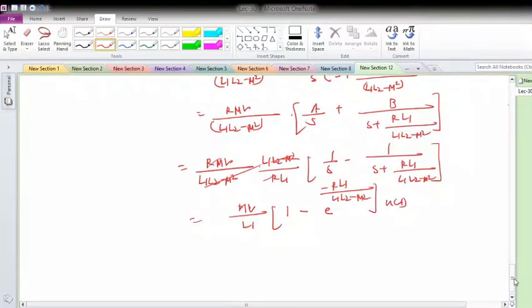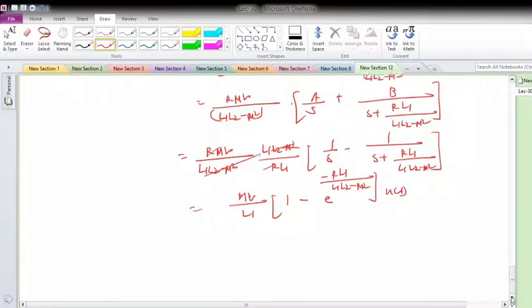Okay, so if we apply an input, and that input is a step input, for example, what we'll get is an exponentially increasing form with some time constant. And why with some time constant? Because of the energy storage element, that is the inductor present over here. So if I would like to draw the graph, what is the input? Input is my step input, and this is v1 of t, and what will be v2 of t? I'll get this. Okay, so this will be my v2 of t.